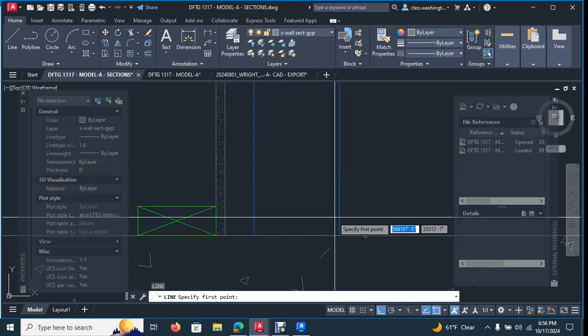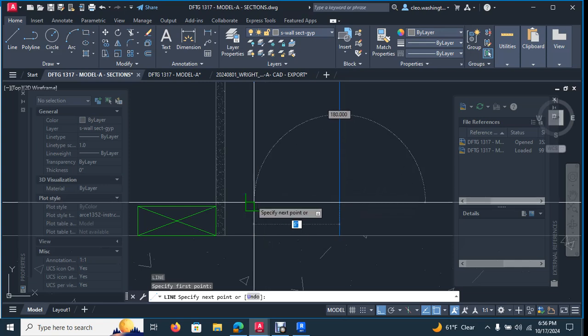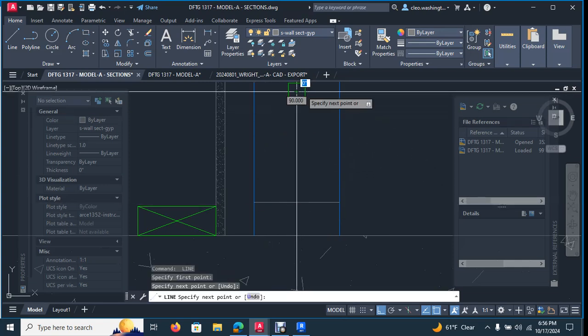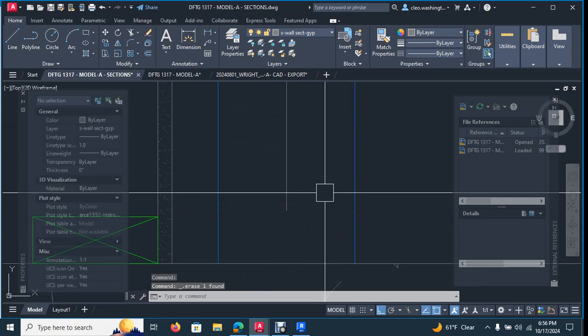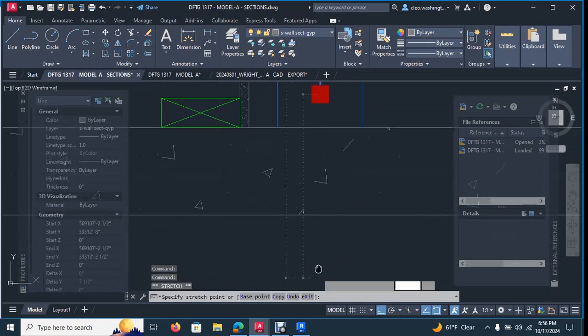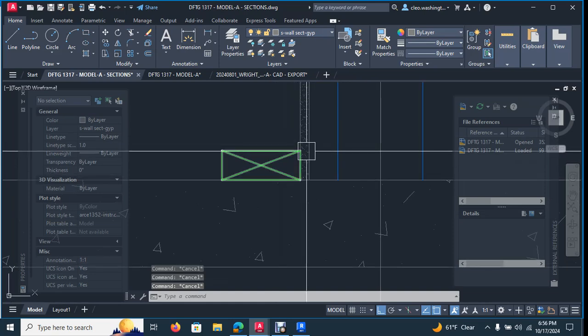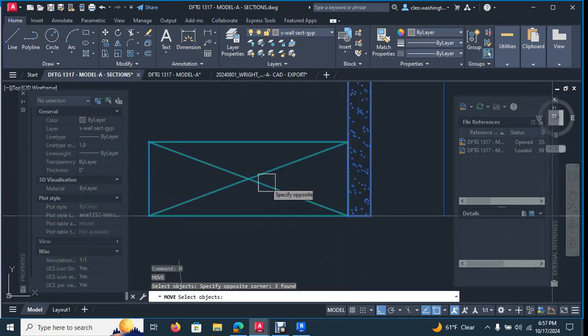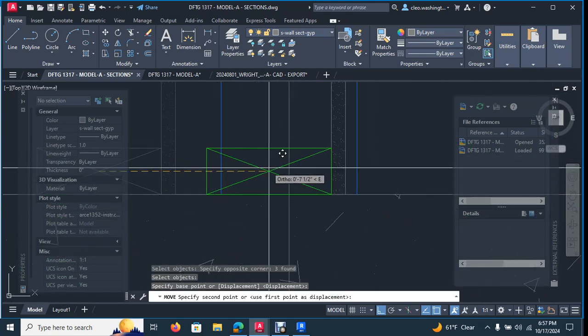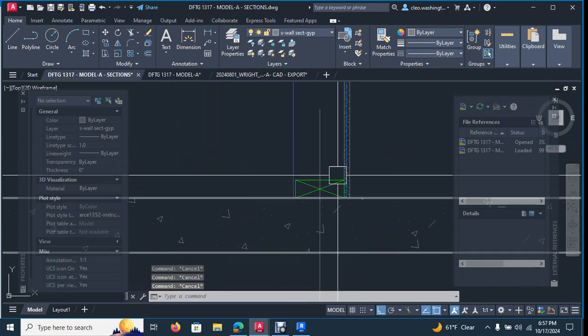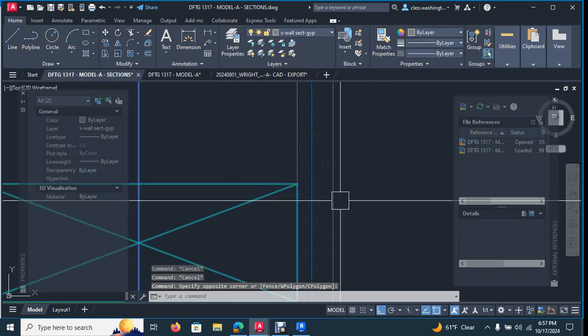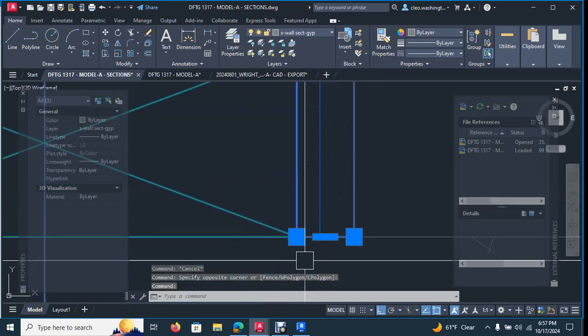So what I like to do is sometimes I'll just draw a line. Then I'll draw a line up to give me my center line. And some people say that's a little bit elementary, but you have to find out what works for you. Especially with AutoCAD, it's just easy to just draw a line. Now you can take this one and place it here, okay? Now you can take this one, and then copy it.